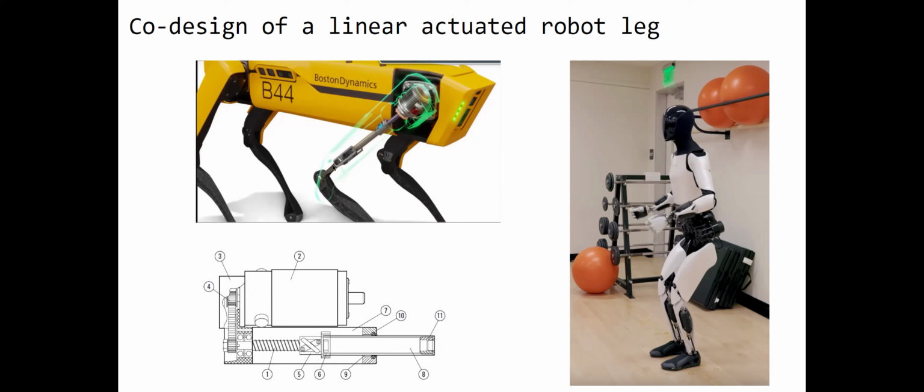What's the key thing here? Why not a rotational link? Why not just place a 4-bar linkage with parallelogram geometry to move the leg? The idea lies in back drivability. What's back drivability? It means that if you move not the motor but the leg, it starts actuating the motor itself.